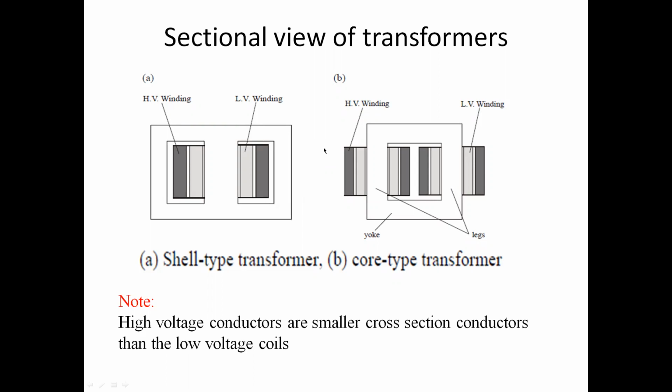The next reason: HV means high voltage, so high electrostatic fields are there. Due to this, electrostatic force is produced in the core and they deform the core. That's why we put some distance, first LV then HV. Then these forces may be reduced and your core will not be deformed. Due to electrostatic force, when we pass current through a transformer, it creates some humming sound also due to this force only.